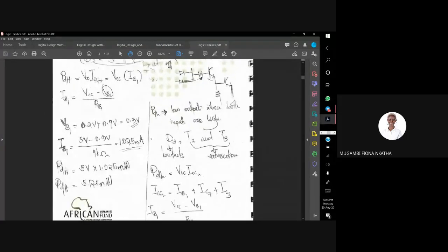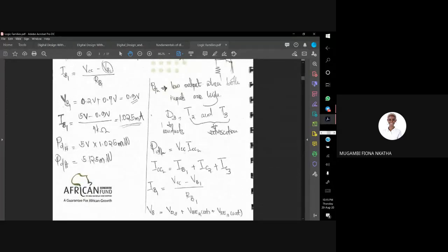Please, if you have a question, don't hesitate to ask. So our IB1 will be equal to VCC minus VB1 over RB1. When we have a low output, our VB1 will not be the same as our VB1 when we had a high output, because these are very different conditions.